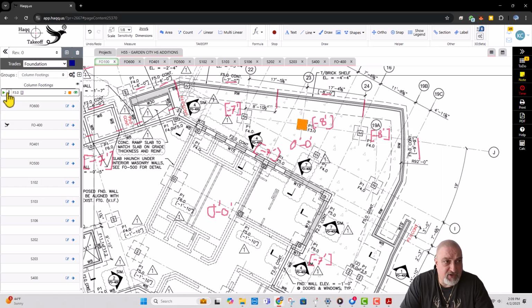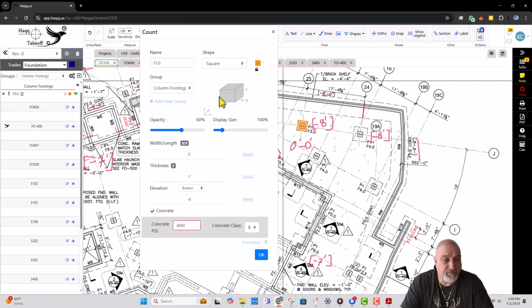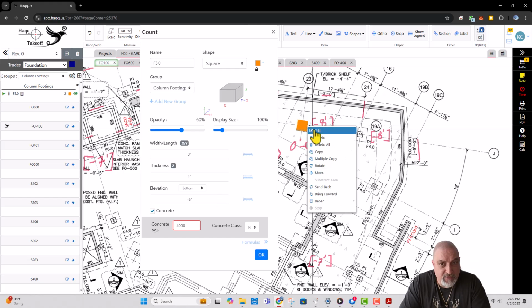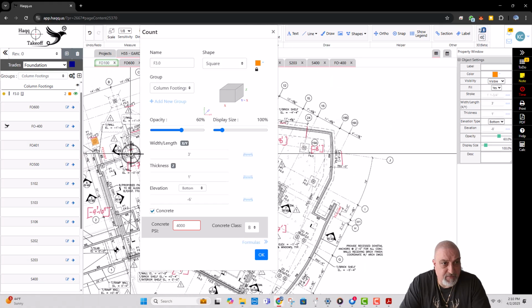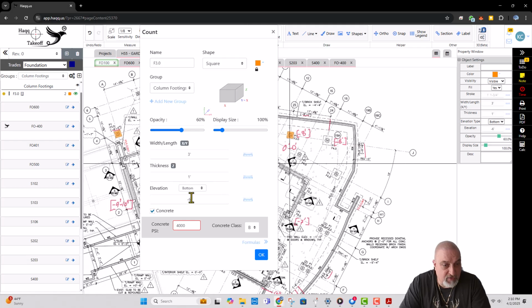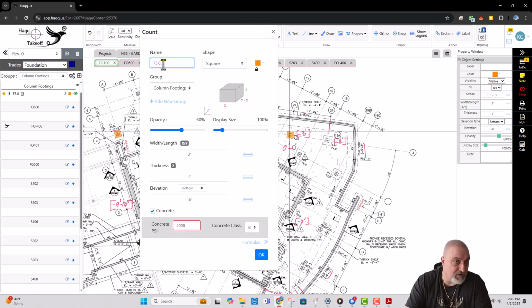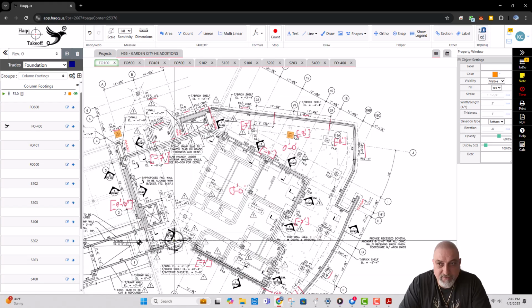But if you have to make any change from here at the main edit menu entry form, in this form, if you need to make a change, remember, let's look at it here. Look, the bottom of footing elevation is here -8, and the bottom of footing elevation here is -6, because the original entry was -8. Now go back to this one. We changed this to -8. When I make any change, even changing the name or something, or you didn't even make any change, you just click on OK.